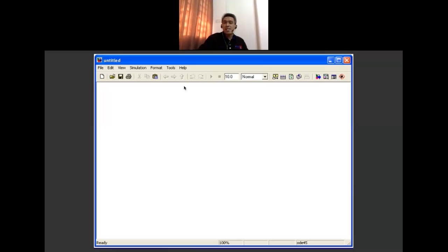So how do we model electrical or electronic circuits using MATLAB? First we have to find the components or devices that we have to use. Where to find components or devices in Simulink? You can find them at the Simulink Library Browser.